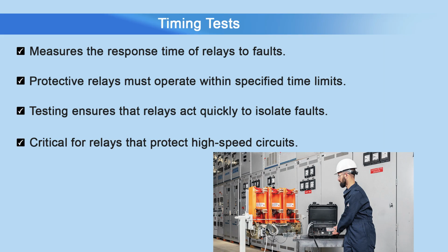Next, we go for the timing test. This is done to measure the time it takes for the relay to respond to a fault condition. This involves applying a fault condition to the relay and recording the time it takes for the relay to operate.